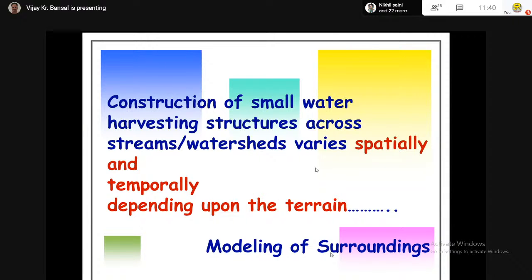and site identification. So there are so many applications of this. It has been used to find check dam locations, like on a Hamirpur map, these are the locations of check dams, and drainage basin maps. Earthwork planning: for this particular building, from where cutting will take place, where filling will take place, and how much will be the volume of that cutting. Then identification of location for a dumping site or nearby location for dumping of this material. Okay, so this is just the last example.